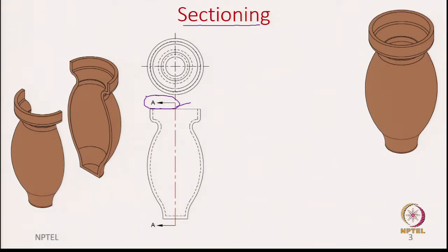So, for example, here we are showing you that this vase is split into two pieces using the imaginary cutting plane. So, I am stressing the imaginary cutting plane because what we are doing is a hypothetical situation where we are assuming to split the object, not going and splitting it in reality. Okay. So, now you can see a lot of inner details once you section this object.